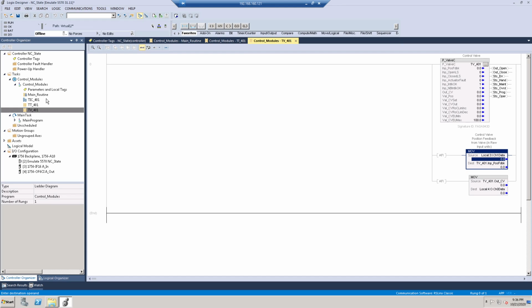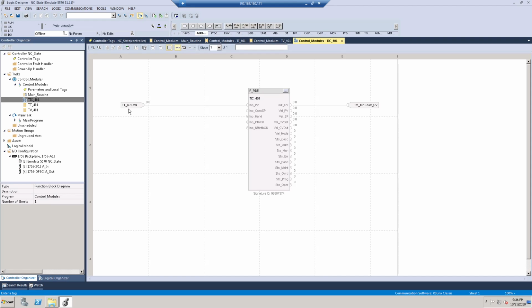So what that's saying there is that, I'll go into this detail with the PID block, but pretty much this PID block will be set up to, I'll just go ahead and show you now. But this temperature value is going to be fed as the input PV to this PID block. This automatically, based upon the configuration setup that we'll set it to, it will automatically do all of those Laplace transforms and whatnot and calculate the control value that we need to set for that flow valve.